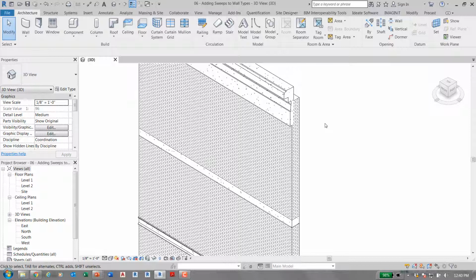Cool. All right, why would we add sweeps in a wall family or reveals in the wall family? I gotta make it pretty. It also is going to be because these walls and these sweeps and reveals are for the entire place of this wall, right? It's every place this wall exists. What happens if it's just one place? Do you just create one wall family for that? I'm getting the front row saying no, but nobody else is committing. The answer is no, we don't. We would just add a wall sweep or a wall reveal to that individual wall. Okay, is what we would end up doing.